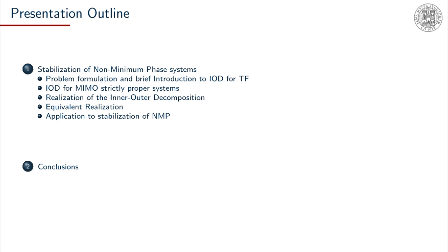So during this presentation we talk about the stabilization of non-minimum phase systems. In particular, I will give a problem formulation to introduce the problem we want to solve, and give an introduction to what the inner-outer decomposition is for a simple example of a transfer function. I will then present the extended inner-outer decomposition for multi-input, multi-output systems that are strictly proper.